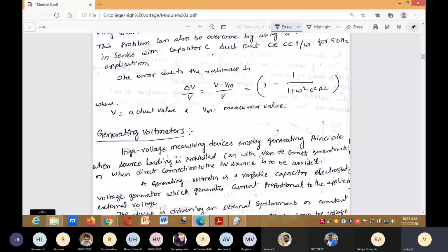The different sources that contribute to the error are: first, the effective value of the capacitance being different from the measured value of C; next, imperfect rectifiers, which allow small reverse currents; non-sinusoidal voltage waveforms with more than one peak or maxima per half cycle; and deviation of the frequency from that of the value used for calibration.